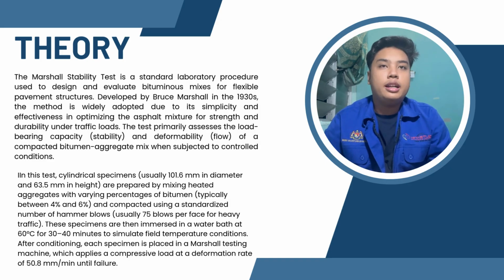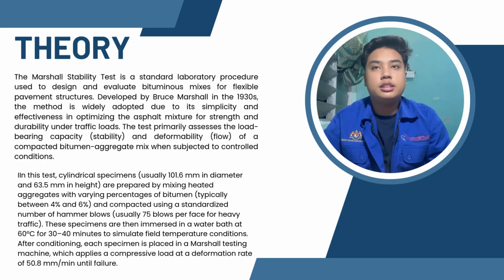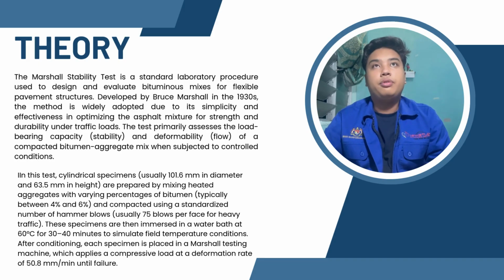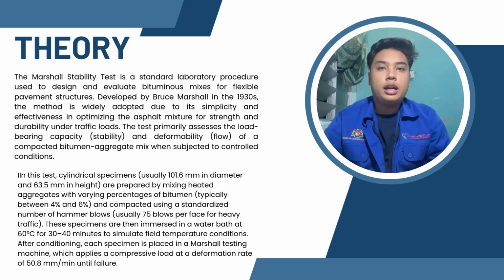These specimens are then immersed in a water bath at 60 Celsius for 30 to 40 minutes to simulate field temperature condition. After conditioning, each specimen is placed in a Marshall testing machine which applies a compressive load at a deformation rate of 50.8 mm per minute until failure.